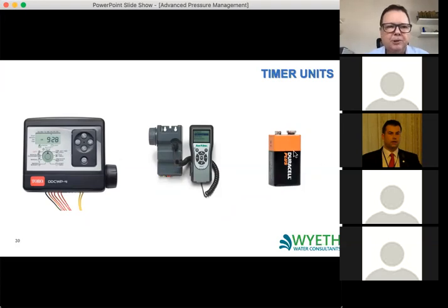So if you put these batteries in, you really only need to do preventive maintenance, about changing the batteries once a year. And that's to be really safe. You could go for about 18 months and see how that goes. The other thing about these timers is they generally tend to be IP68, which means they're waterproof. And if you have PRVs that are installed underground in chambers where you have a chance of it getting wet or flooded, these should work okay most of the time in those wet or flooded chambers, as long as they're not underwater for a long period of time.